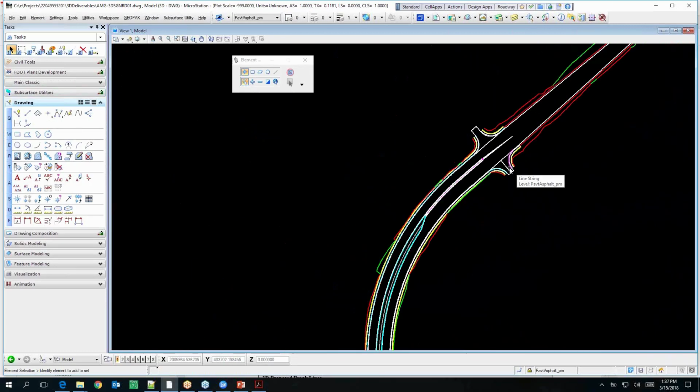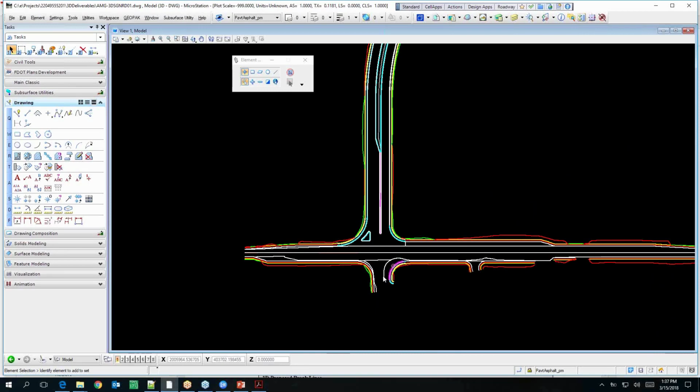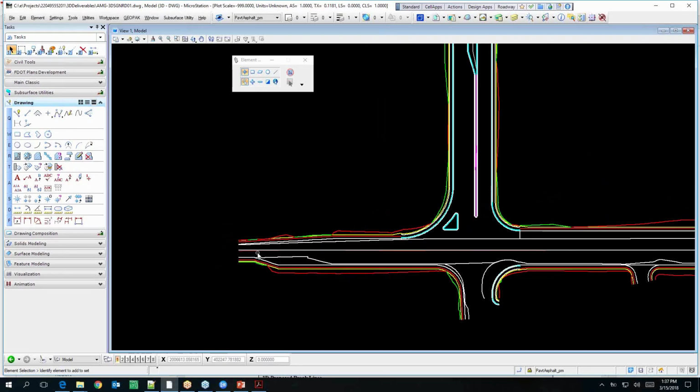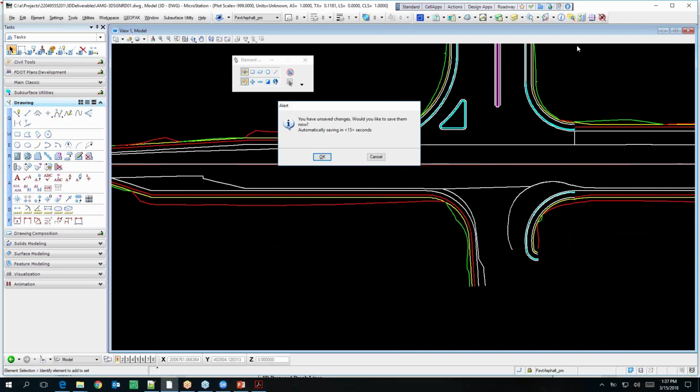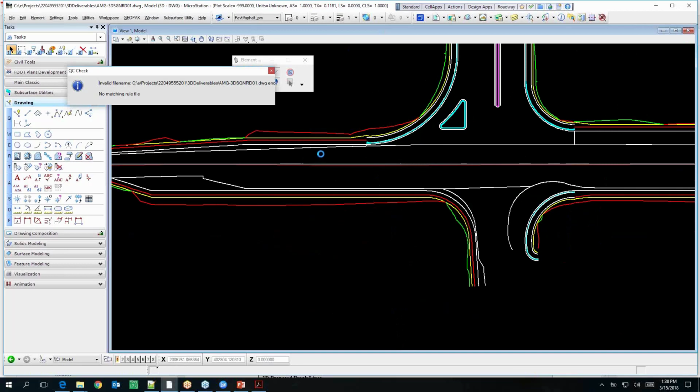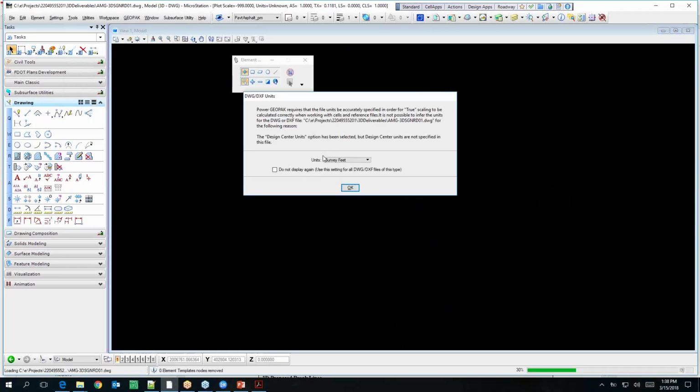It will throw errors in these areas, mainly when they're crossing. Not necessarily when there's gaps, but when they're crossing. It doesn't like when two lines intersect directly above one another, or if they're crossing. Two elevations don't work on a terrain model, right? Yeah. It would be one XYZ location. So if you think about it, there's possibly two Z elevations when you do that. Or if you do this. So everything has to be pretty clean, or else it'll throw errors. It'll still pick a point to create a surface from internally, but then it'll throw you an error.